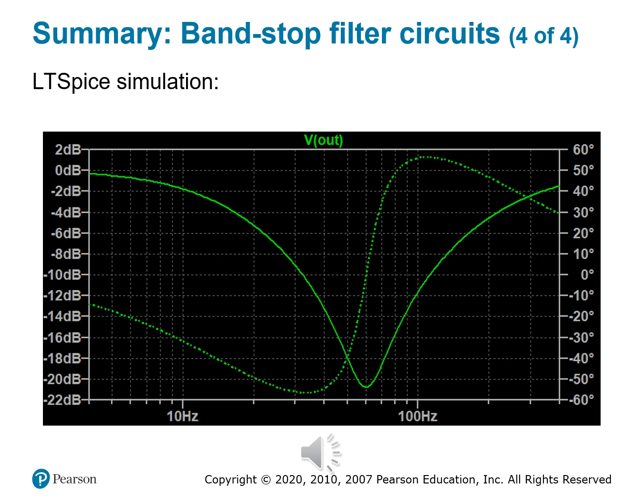You're going to see the green truth, the magnitude and the phase. The solid green line that you see there is your magnitude response. The dotted line is your phase response. And what do we see? Right around 60 hertz, the magnitude line dives and hits about negative 20 dB. That confirms our maximum signal rejection at that designated notch frequency, which is 60 hertz. So 60 hertz is what we're targeting, with our 101 microfarad capacitor and our 70 millihenry inductor, and that's it.